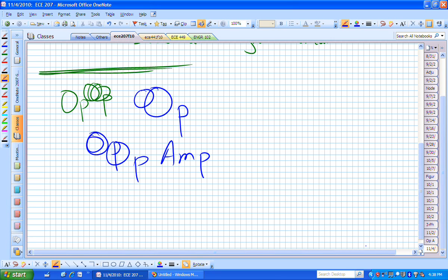We know that I sub 3 is R2 over R3 I2, and for R sub 4, because of KCL at whatever node we labeled it, node 2, we knew that I2 plus I3 was I4. And if we can put everything on the right in terms of I sub 2, that's the same as I1, and we know what I1 is in terms of Vn. That was our first equation. And let's now just do that.